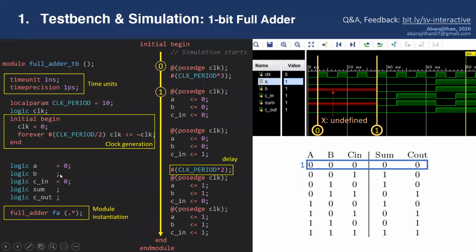As a result, it is an unassigned wire, so the value that B gets is X. X means undefined. You get these red lines when you try to assign two things to the same wire, or sometimes if you don't assign anything to the wire.